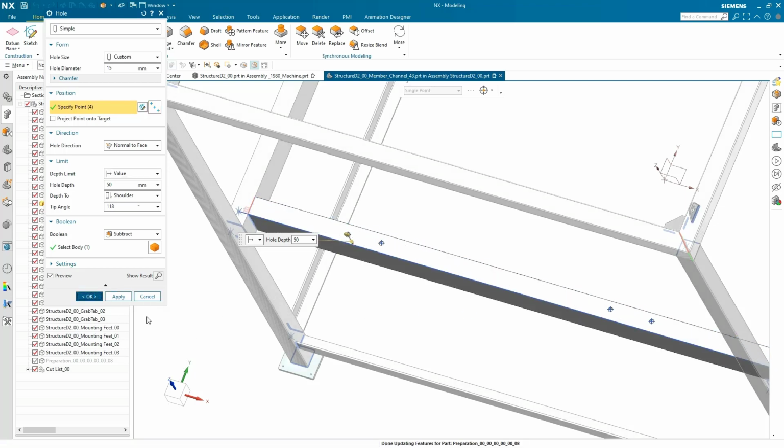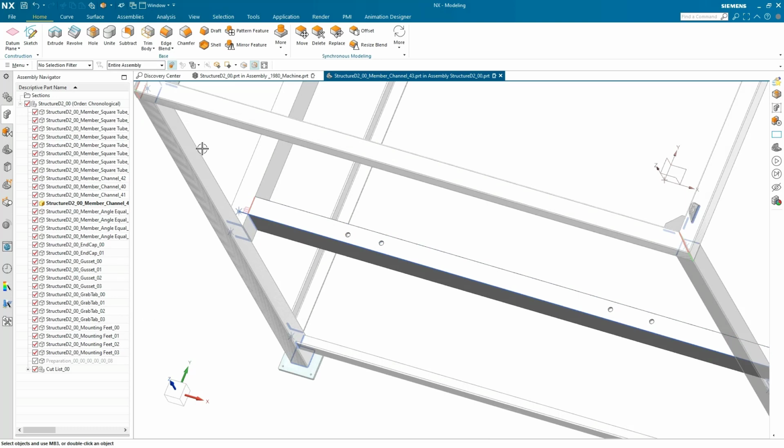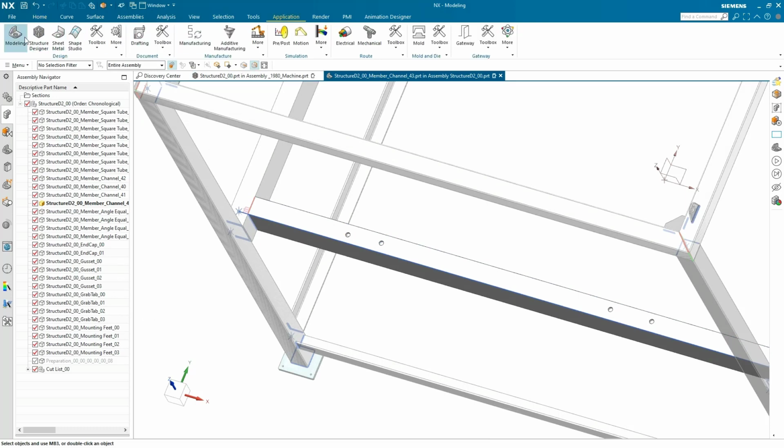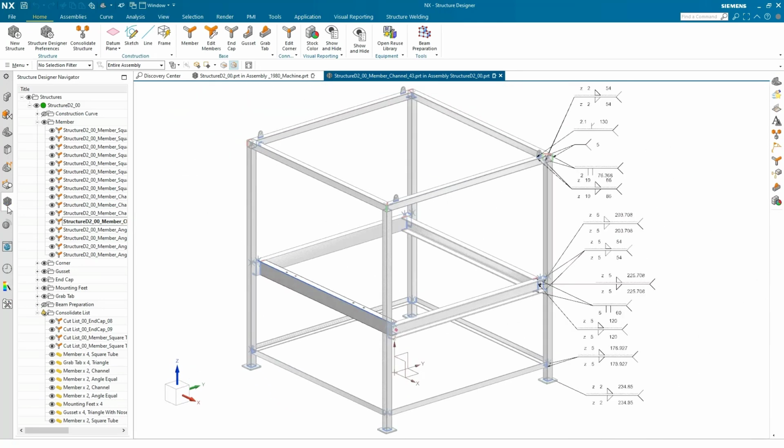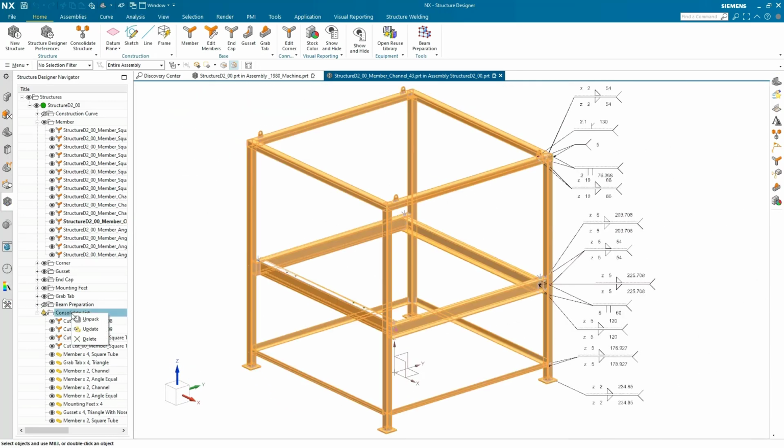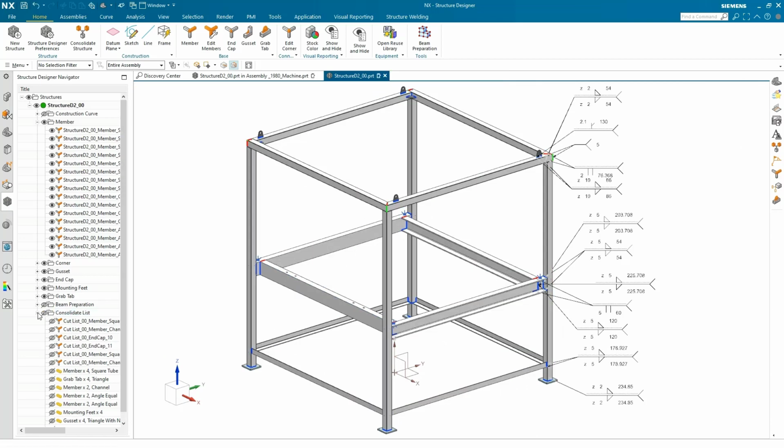The consolidation operation looks for geometrically identical parts, and if a part is, say, mirrored, the system is smart enough to consider them different. Because of the newly added holes, this member is no longer geometrically equivalent to its counterpart. Watch as the process removes this component and places it in its own group. A quick selection of the members shows it's now a unique component.